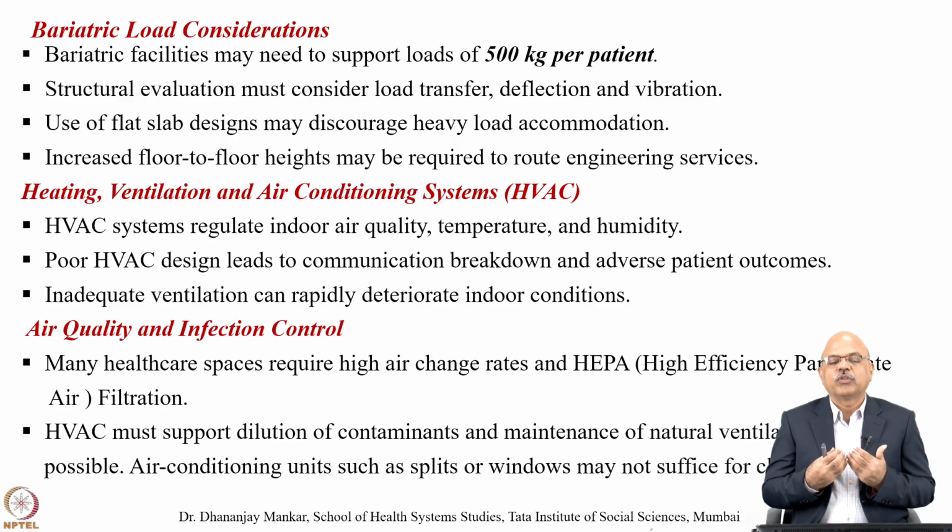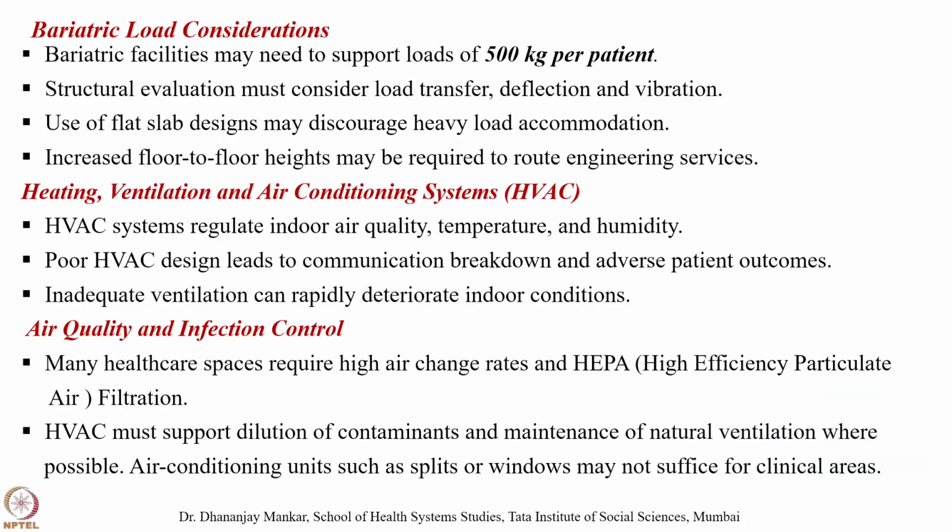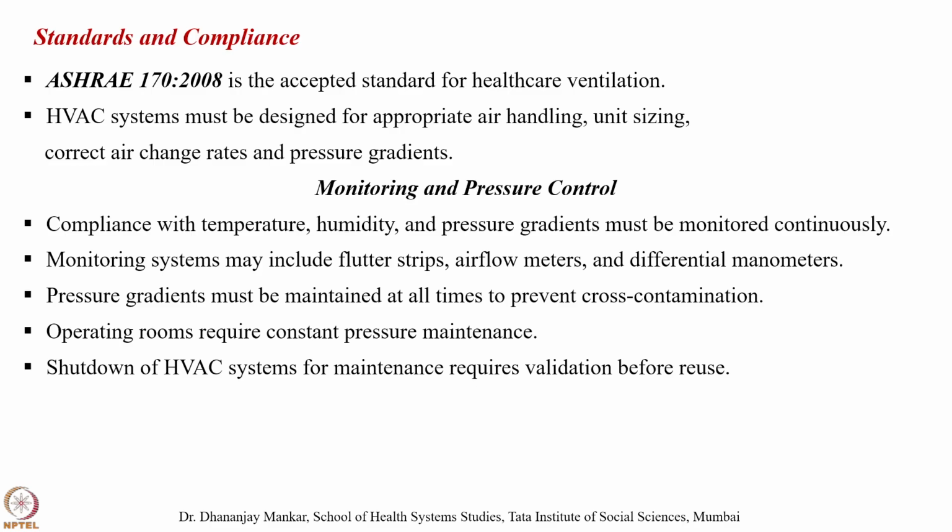With respect to HVAC, which regulates indoor air quality, temperature and humidity, poor HVAC design can lead to communication breakdown and adverse patient outcomes, which are issues to be taken seriously. Inadequate ventilation can rapidly deteriorate the indoor condition, and many healthcare spaces require a high air change rate and HEPA filters, where the HVAC must support dilution of contaminants and maintenance of natural ventilation where possible. Air conditioning units such as splits or windows may not suffice for the clinical areas, and you need to work on this in the planning stage for these departments.